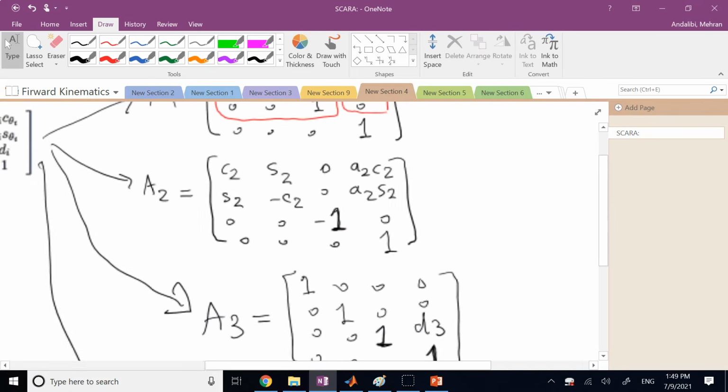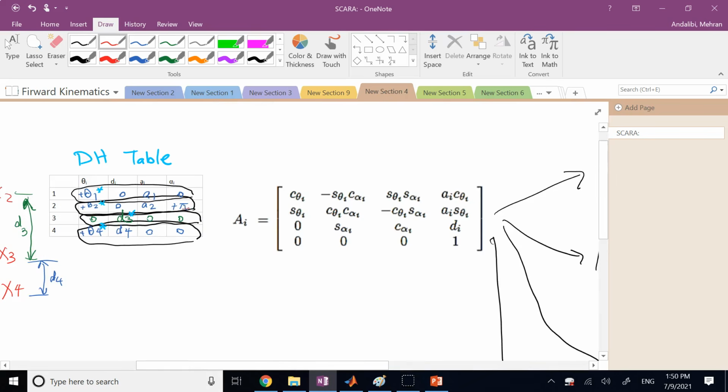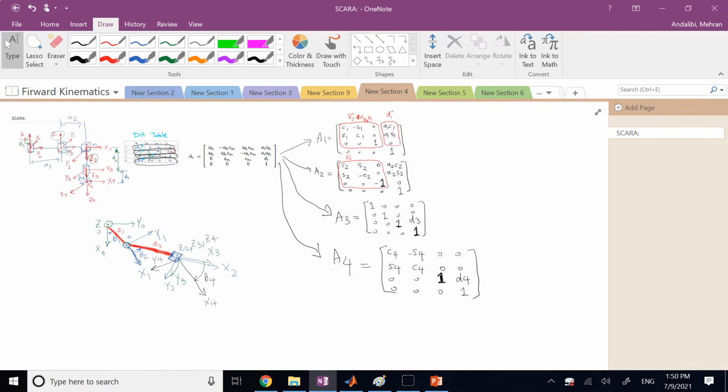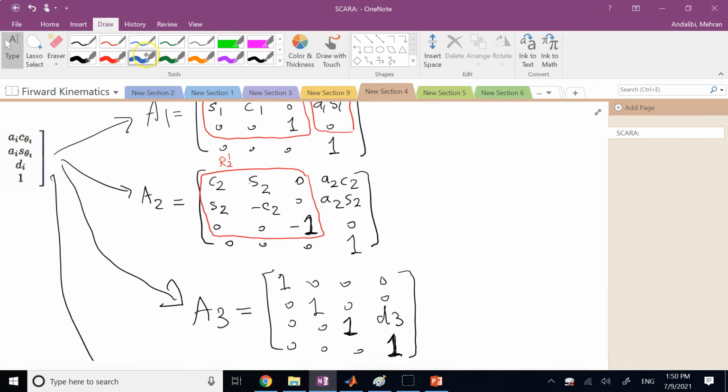Now, when we go from frame 1 to frame 2, the rotation looks like a Z rotation, except that it has some negatives in it. So this is the rotation of frame 2 with respect to frame 1. It looks like a rotation Z with angle theta 2, except, as I said, first of all, this has to be a negative sign, not this one. Negative cosine, so this negative should go up there, and this should be positive 1. So why is it like that? That's all because of that spin, the twist, pi. The pi twist that you see here, it's just because of that. Now, does that make any sense? Well, let's take a look here. What's the meaning of, let's say, this third column? What is this? This means how I can write Z2 in terms of what?